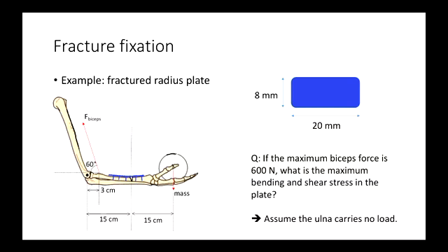If you imagine this plate, we've just cut it in half. It's in equilibrium because it's not falling. What forces would be inside that plate keeping it in equilibrium? Shear force, yep. So shear force like that, call that V. And a moment. Call that MV.